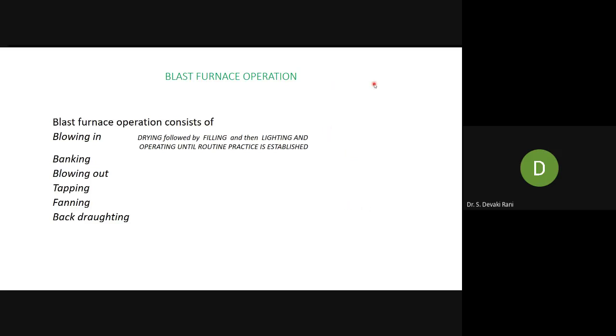The gas comes out from the top. From the top you are getting the gas. What properties do you need for the gas before it goes into the gas cleaning system? What are the required properties you want to know? BF gas is what is coming out. And what is the composition? CO and CO2, ma'am. N2. So what is the CO by CO2 ratio? Will CO be more, or CO2 be more? CO2 will be more, ma'am.